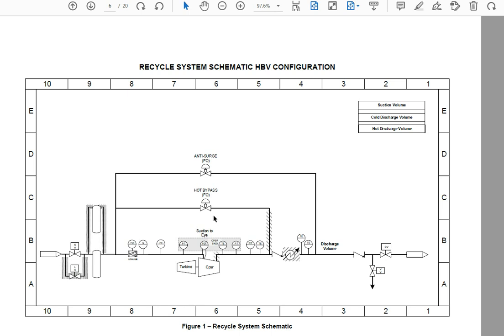They're available on the web to model my valves. I also input a time delay to begin opening and then a time constant to open to 63.2%. So I describe how quickly the valve is moving, and then I use the CV curves depending on the trim type to model how much flow capacity the valve has.